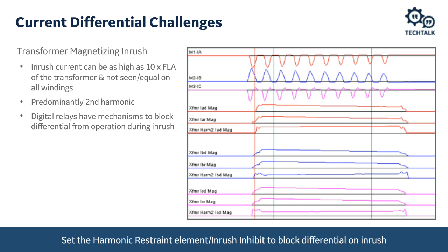Which setting you select depends on your transformer and how much security you want. So for newer transformers, 1 out of 3 is okay. It's less secure, but newer transformers are more likely to operate predictably. For older transformers, we usually suggest 2 out of 3 are average, which end up operating pretty similarly, average being slightly more secure. We usually advise against using the per phase since it has a higher likelihood of causing a misoperation, being that we're looking at and blocking essentially in a single phase fashion.